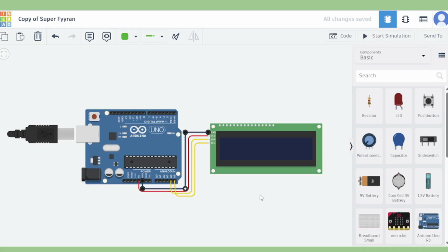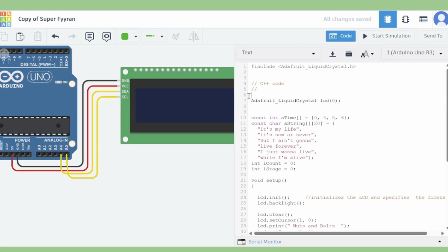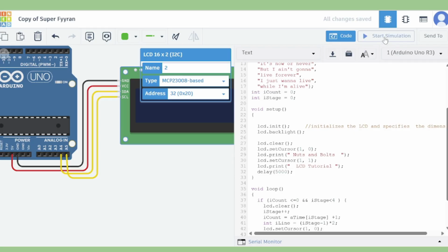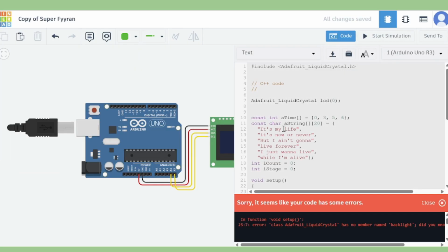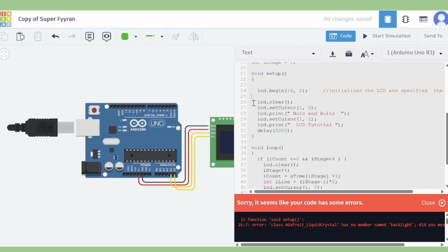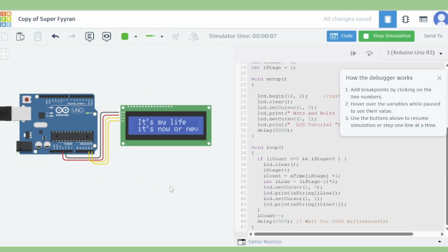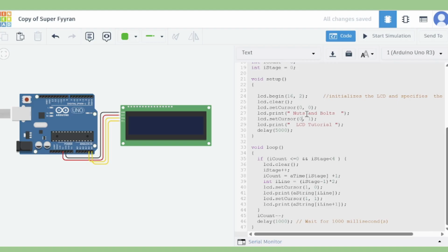I've encountered cases before where switching to the LCD I2C version in block mode would also result in no display. My simple guess is that the simulator supports the relevant library during compilation, but the display functionality hasn't been fully developed yet. I've listed my Tinkercad project in the description.